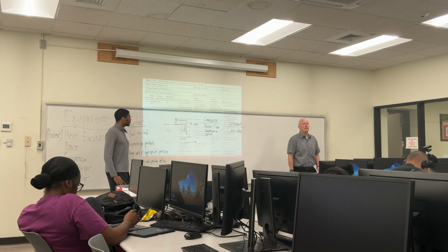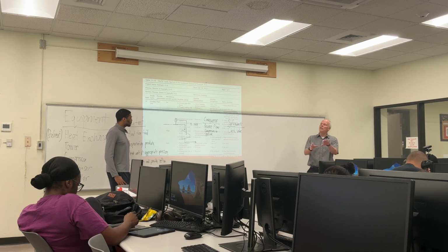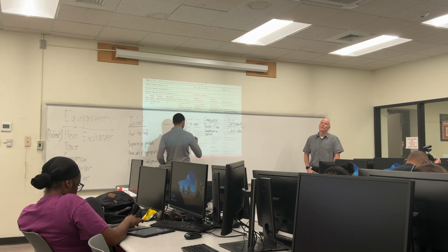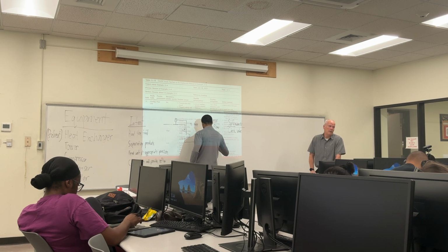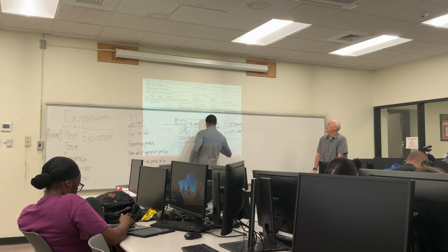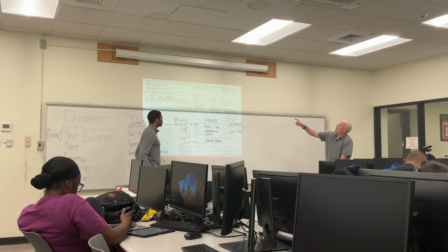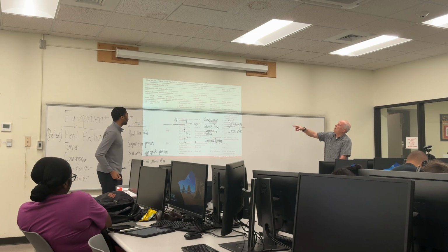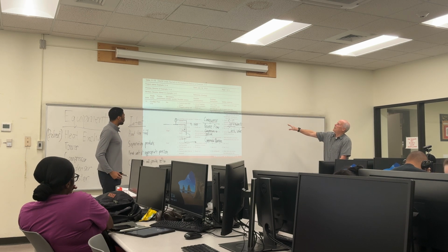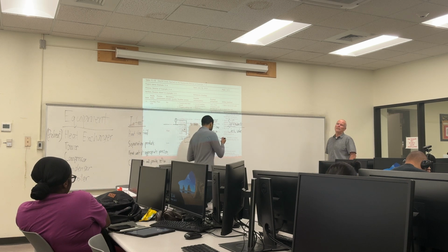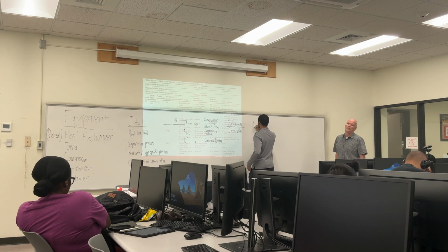Plus, those compressors have thrust bearings, and thrust bearings are generally in one direction. It won't work too well if you try to run that thing backwards. It'll break something if you do that very long. So compressor damage is a very real possibility. So, do you want to talk about action required or possible causes? Well, let's talk about action, because we're terrible at action, because we're not operations, and so this is our worst one. So what's the action required?